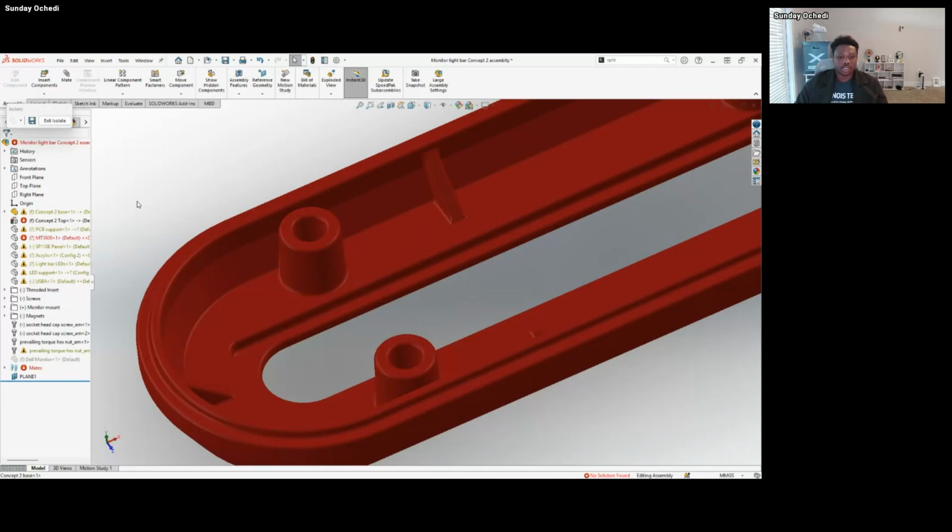But when you're talking about tolerancing and you're planning to have someone manufacture it, you have to ask them the type of tools they have. For the holes you're going to put, you consider between what level, plus or minus 0.5, can it still fit? If at minus 0.5 it still works and at plus 0.5 it still works, then that's your tolerancing for that part. It also boils down to what your manufacturer has.